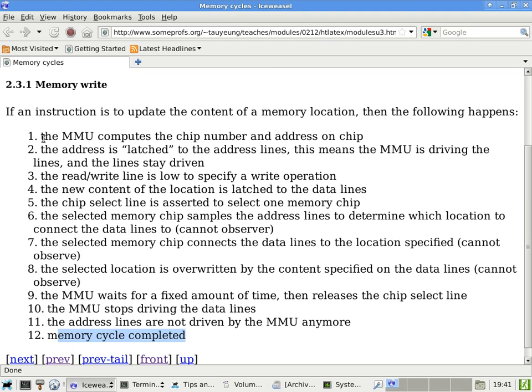Yep. They're still faster because they run at higher clock rates. DDR2 and DDR3 run at, quote-unquote, a higher clock rate, but not exactly. They're basically using both the rising edge and the falling edge of the clock to synchronize the operations. And I think with DDR3, they can also do synchronization between the transitions, and that's why it can speed up the access. But when you are setting up the address line, the data lines, and also the chip select line, I believe those operations still have to land on top of the edges. They cannot be off the edge.